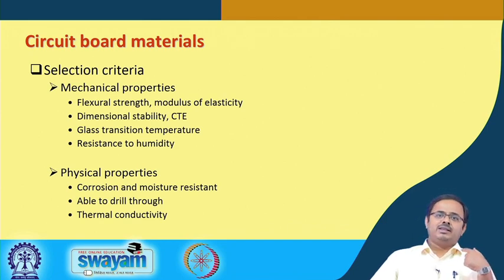Here I take you back again to our discussion in first level packaging, where in flip chip bonding we talked about the underfill epoxy. Remember what was the primary function of that underfill epoxy? It is because the solder balls that are connecting the silicon to the substrate, which can by the way be a printed wiring board material, an organic substrate, are undergoing a lot of thermally induced stresses because of the mismatch in coefficient of thermal expansion between silicon and the substrate.